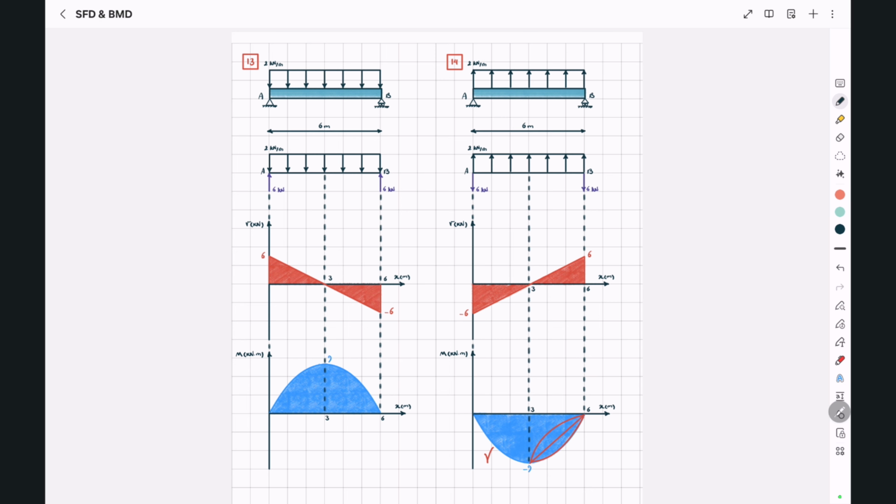In the upper curve, the slope is decreasing, while we know the intensity of the shear is increasing, so the slope of the moment diagram also has to increase. So these two diagrams cannot represent our moment diagram. And this is how the moment diagram will look like between points C and B.